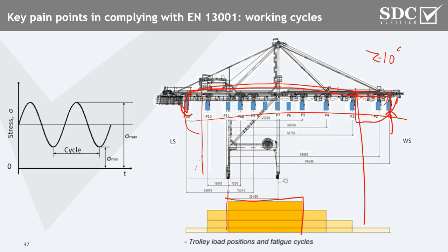In this example, it occurs between the legs and slightly going beyond the hinged connection. So what it means in practice is that the accumulated fatigue damage will of course be much less overall than when you have the trolley traveling from one extreme position to another extreme position. This thing you have to determine accurately.